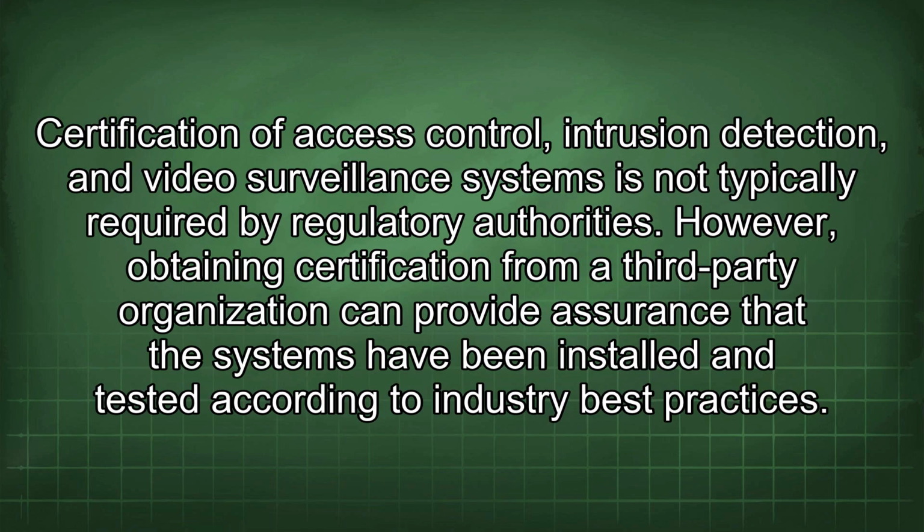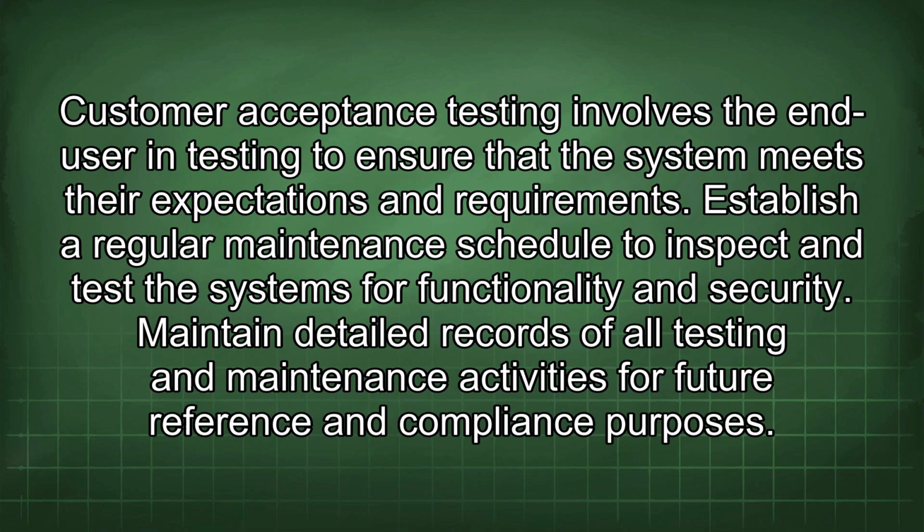Certification of access control, intrusion detection, and video surveillance systems is not typically required by regulatory authorities. However, obtaining certification from a third-party organization can provide assurance that the systems have been installed and tested according to industry best practices. Customer acceptance testing involves the end user in testing to ensure that the system meets their expectations and requirements. Establish a regular maintenance schedule to inspect and test the systems for functionality and security. Maintain detailed records of all testing and maintenance activities for future reference and compliance purposes.